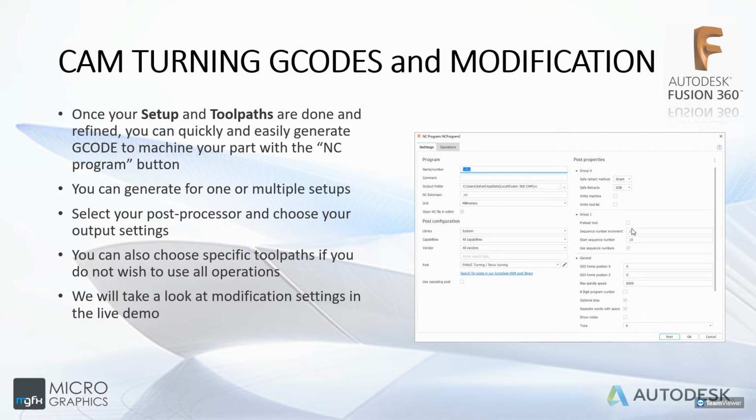Sometimes a simple thing like line numbers can be very problematic. For example, you might have N1 to N500 or N1020, whatever. And some machines are not the newest of machines, and they might have a limit for how long the line of code can be. A simple thing like the N number in front having more digits than it can handle can really bomb your machine and make it unreadable.